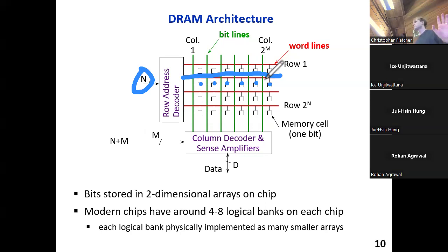And then if you're not accessing the DRAM at some time later, there will be this so-called refresh operation, which comes around and makes sure to touch all of the cells to bring their charge up to the nominal maximum charge. And this refresh operation you can think of as being scheduled along all of the word lines over time in the DRAM.